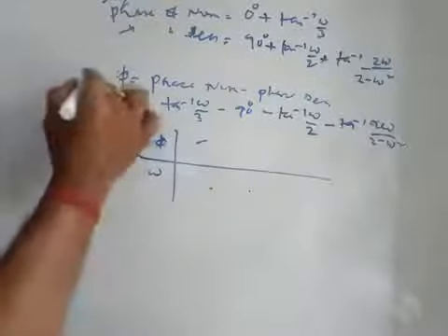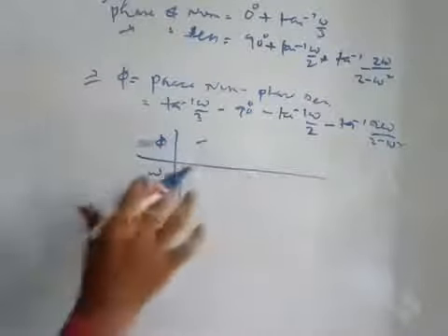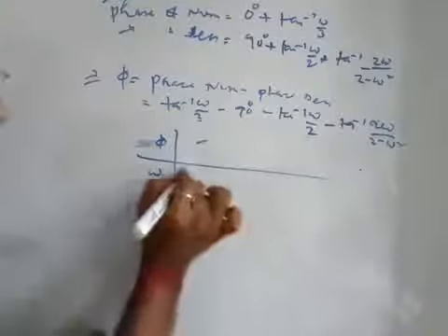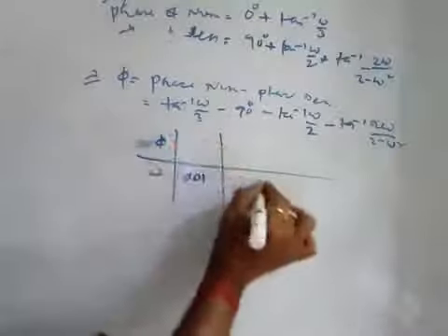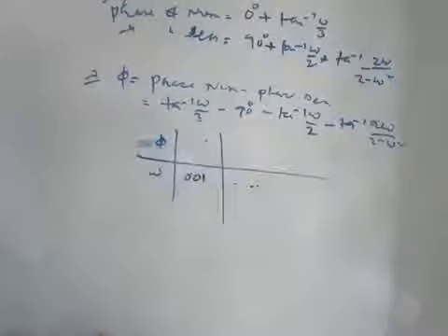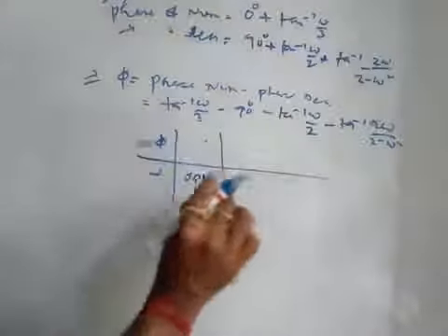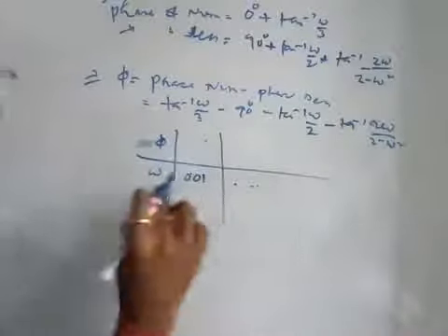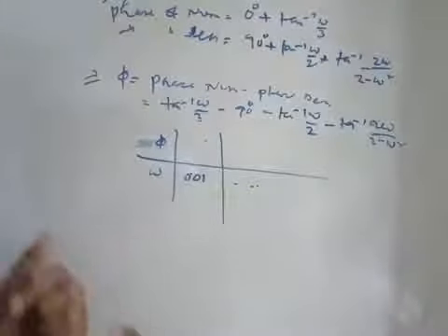So this is the way, and you know how to choose the range of frequencies. That means your initial frequency will be 0.01. Next you have to take the time constant for each term. For each term you will get the corresponding corner frequencies, and you take all these corner frequencies, and in between there will be certain points to get a smoother graph.